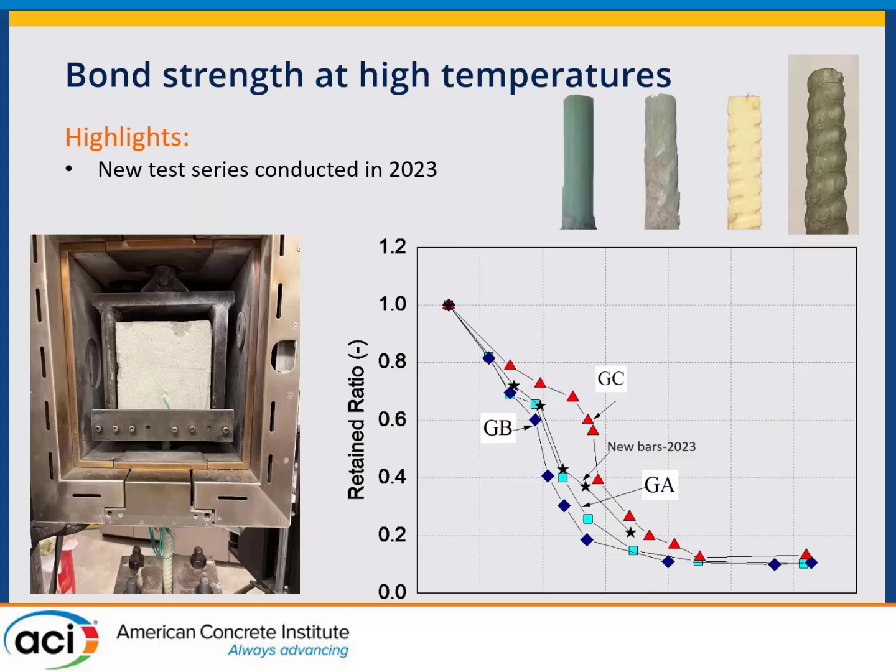And this shows, unfortunately, where we really are affected by the high temperature is the bond of the FRP to the concrete. So it's not so much about how strong the bar is at high temperature, it's how well it's anchored. So unfortunately what happens here is that you get a severe drop in the strength at a little over 100 degrees Celsius, that's like 250 degrees Fahrenheit.